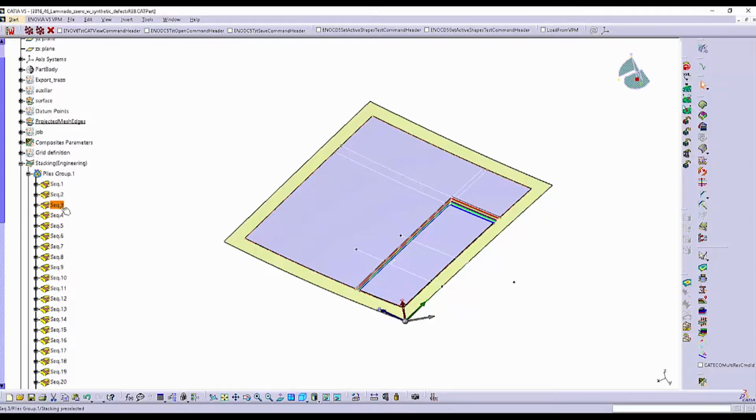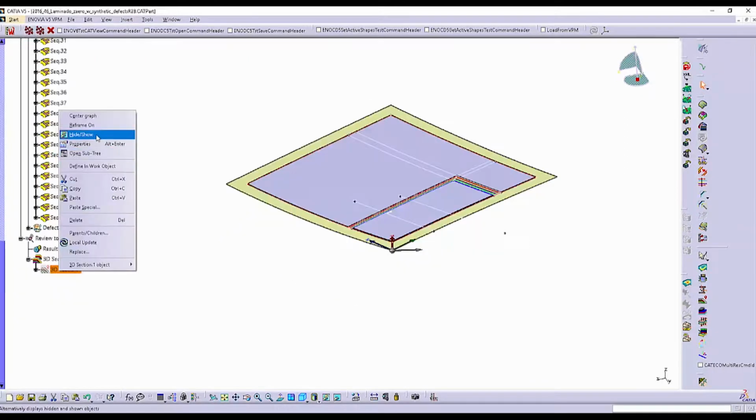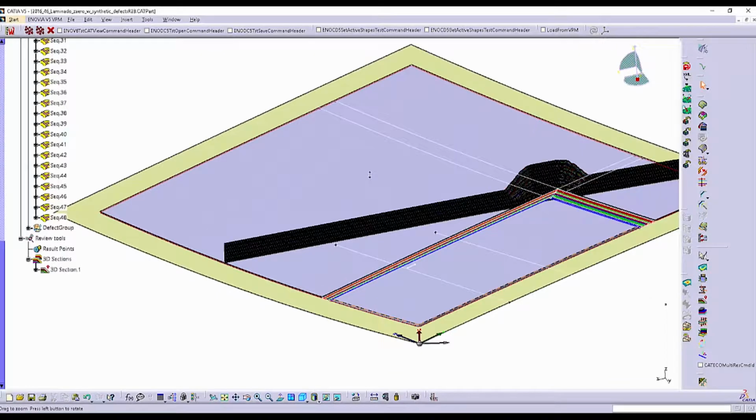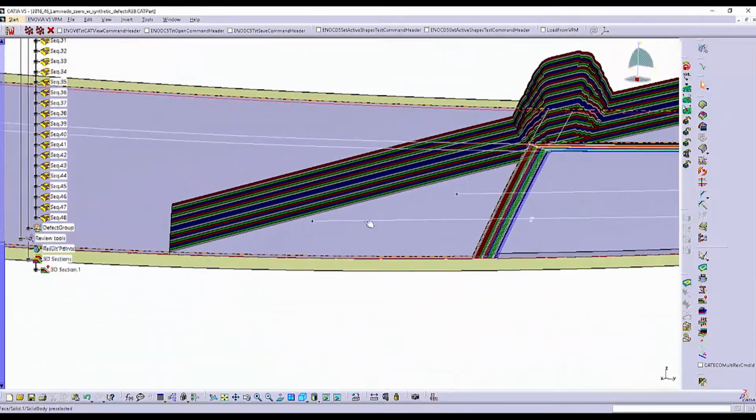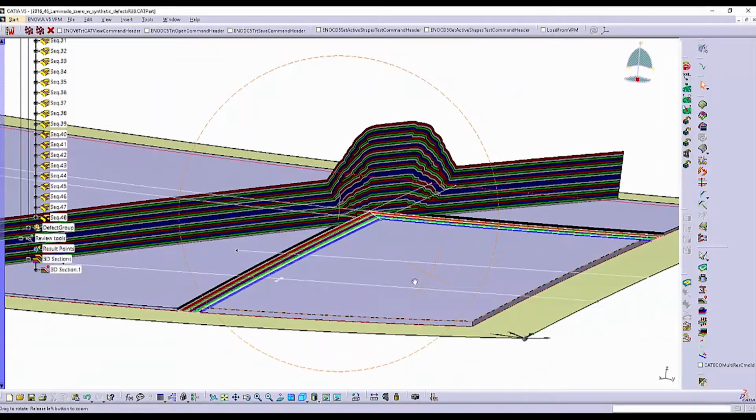To handle this issue, the tool needs to combine the properties of the defect, its size, orientation, type, within the stress field of its location. DS has developed a tool to do this in two ways, an empirical and an FE solution.